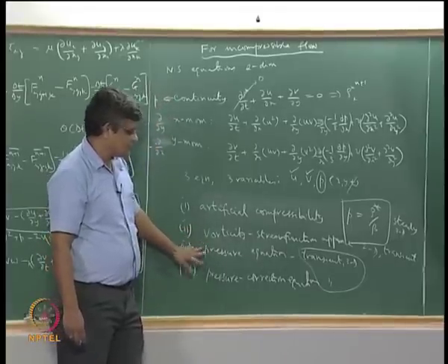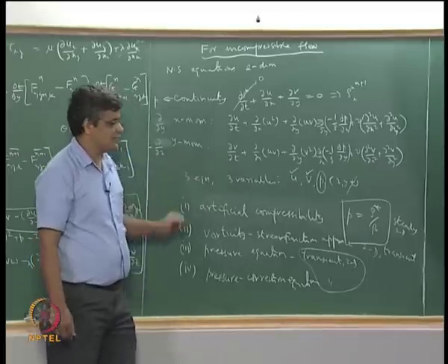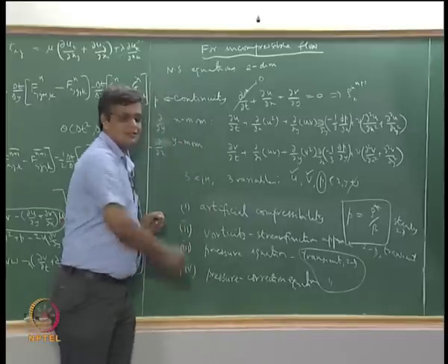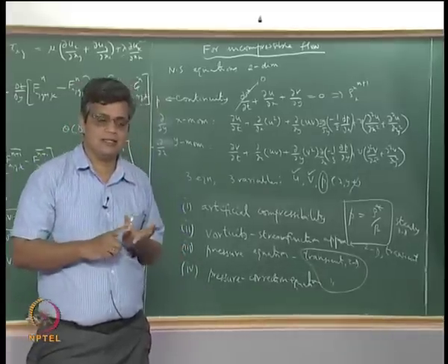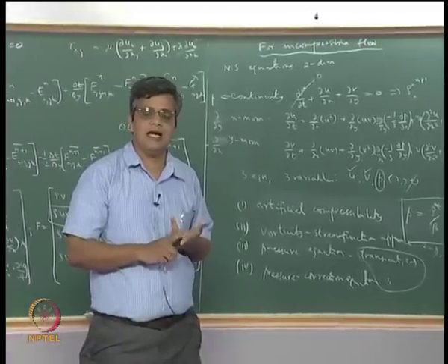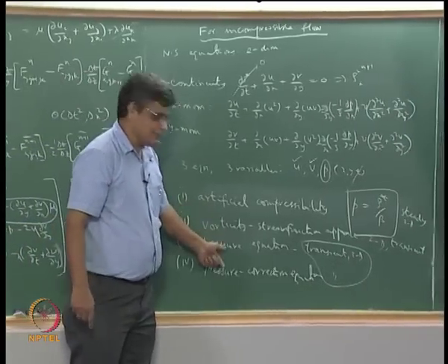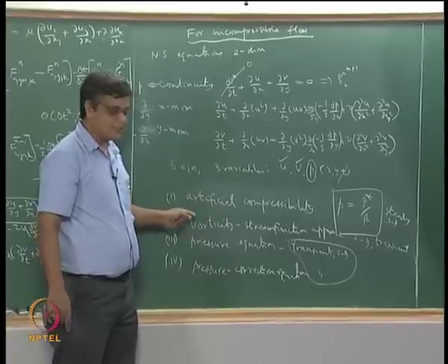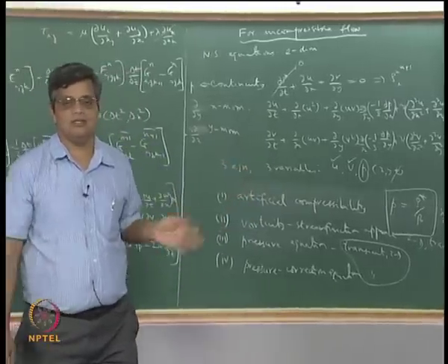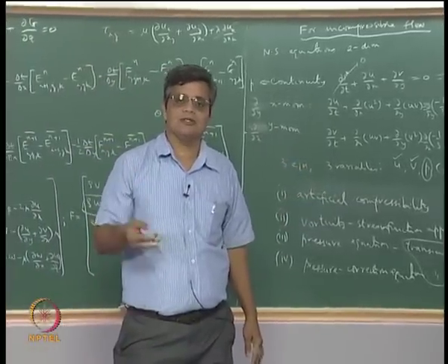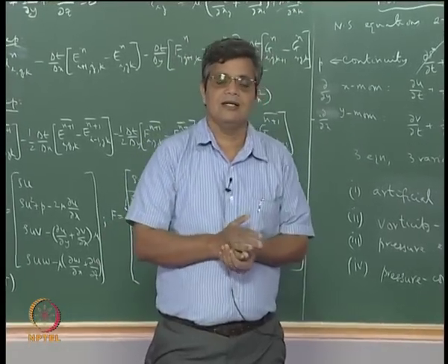So these are the special methods, but the specific aspects of the solution are still common to all of them, because all the 4 methods will involve either the generic scalar transport equation, which has a time dependent term, advection, diffusion, and a source term, or in these 3 cases, in addition to at least one scalar transport equation, you also have an additional either Laplace equation or Poisson equation that has to be solved, and Laplace equation or Poisson equation is a special form of the scalar transport equation for the steady case.